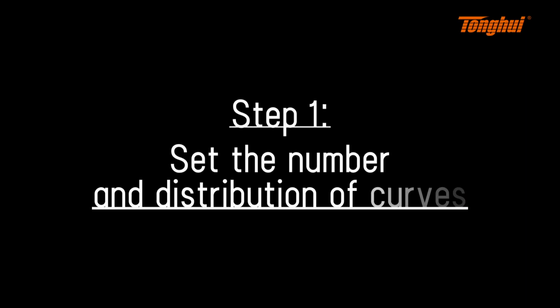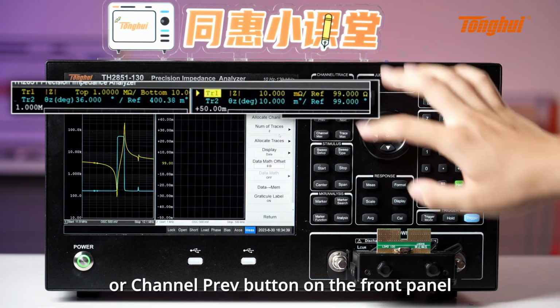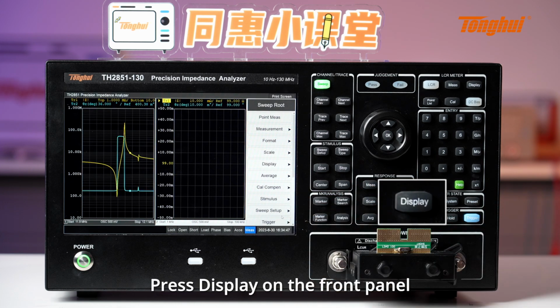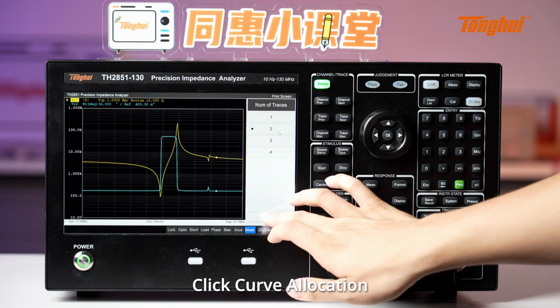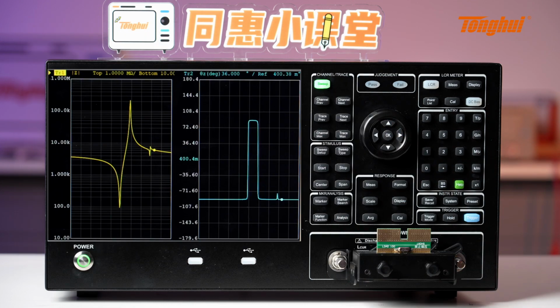Step 1. Set the number and distribution of curves. Press the Channel Next or Channel Previous button on the front panel to switch the channel to be set. Press Display on the front panel to open the Display Setting menu. Click the number of curves to select the number of curves. Click Curve Allocation and select the Curve Allocation mode to be modified.